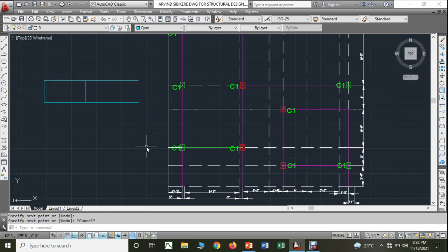Usually, the thickness of the wall that we maintain after plastering is around 9 inches. This is the most common wall thickness that we consider, 9 inches. Usually the wall itself comes around 7 inches if you are using cement concrete hollow blocks, so 1 inch of plastering on both sides will give you a 9-inch wall.